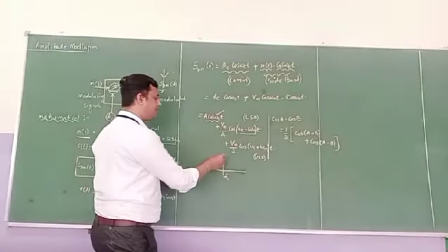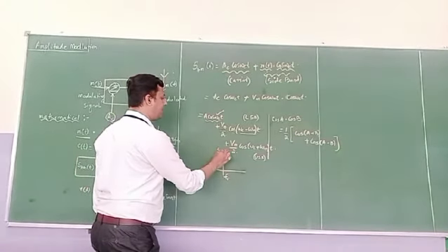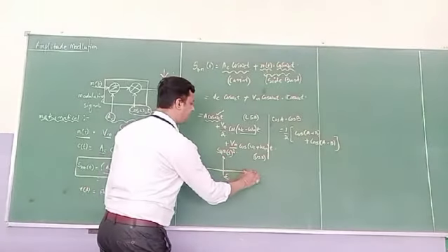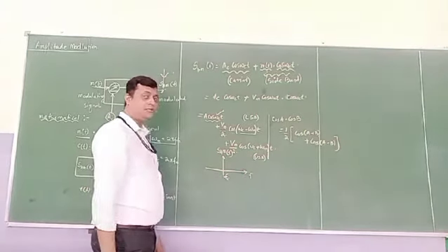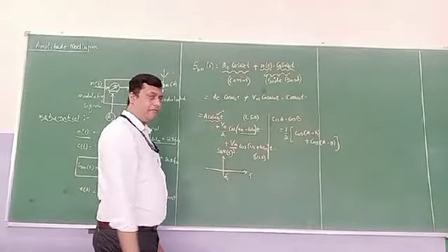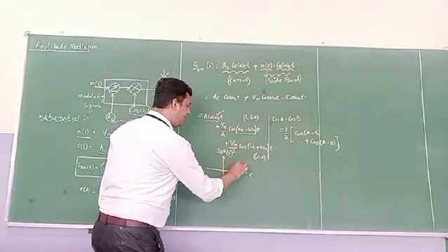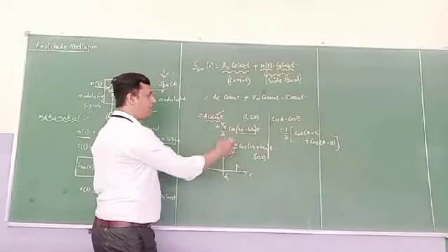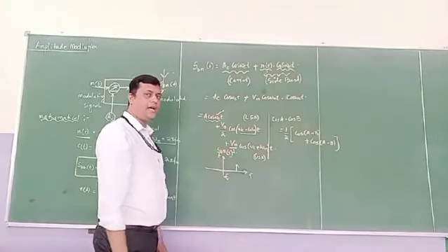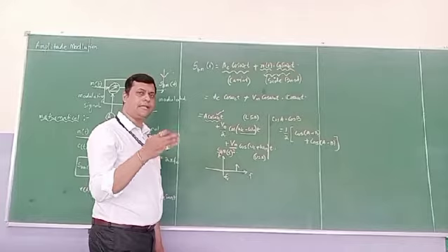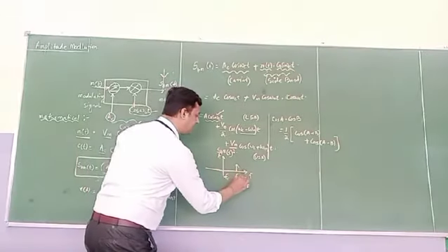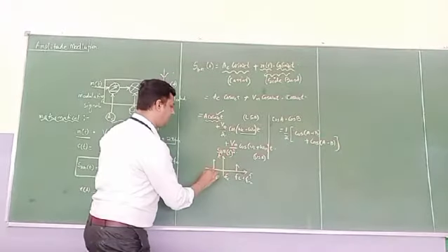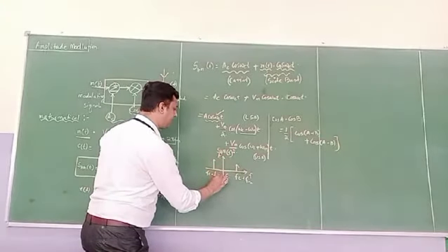For this particular representation, if I am representing S_AM of f in the frequency domain, I will derive all these things. The center frequency is Fc, and the amplitude of this is A. Now omega c plus omega m means it is Fc plus Fm. Similarly, the lower sideband which is available is called Fc minus Fm.